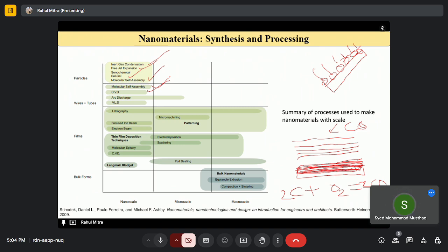So the carbon will form a layer on top of the substrate, and because of the temperature, this carbon will diffuse. If you maintain the temperature above 600 or 650, this carbon will diffuse into the copper or silver substrate, and once the substrate reaches the supersaturation stage, the splitting out of the solid will happen.